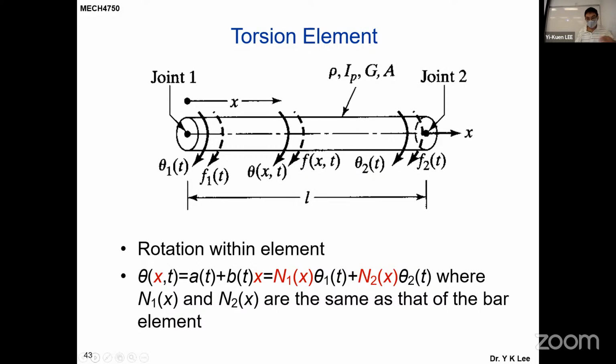And then, of course, we can also repeat the same thing for the torsion bar element, right? And then describe those angular displacements as a function of the two nodes, basically the left-hand side and right-hand side nodes, right? And the angular displacement at an arbitrary point will be a function of theta1 on the left-hand side and theta2 on the right-hand side.